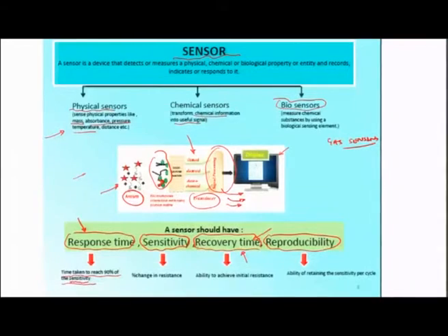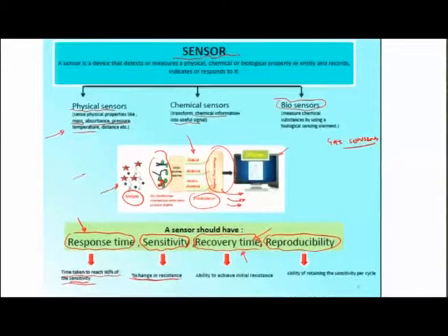In the case of sensitivity, particularly when we are talking about resistive elements in gas sensing, there is a lot of utility of resistive elements, which I'll show you in the next slide. There is a percentage change in resistance that we are looking at as the concentration varies. Supposing we are trying to find this out through a system where we have a carrier gas and the target gas, and we make a molar ratio so that there is a ppm level of gas being injected into the system.